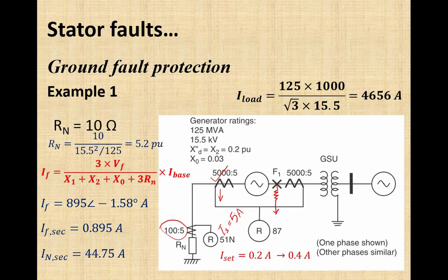Now the question is, a fault which was missed by the phase differential relay can be detected by a dedicated protection in the neutral circuit. Why had it happened in that way? Why has the phase fault relay failed but the neutral connected dedicated CT and its relay has detected the fault reliably? The reason is the CT ratio.